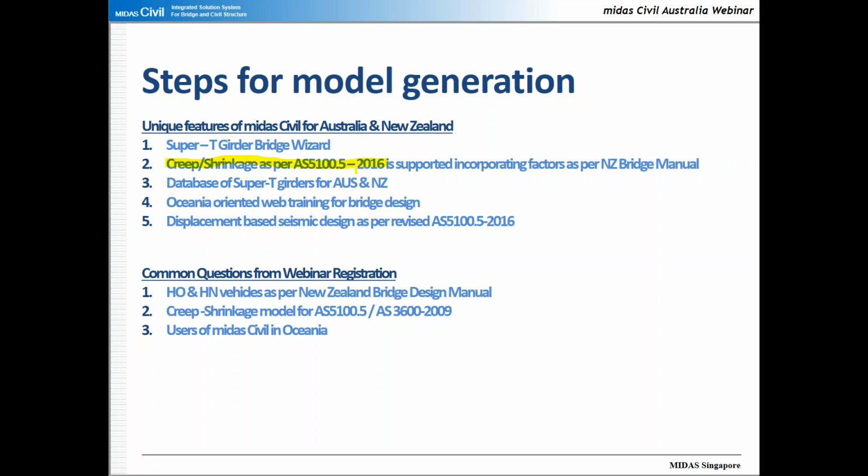And since New Zealand is following the creep and shrinkage model in AS5100 Part 5 with some changes, I would like to mention that you can even incorporate those changes as per the New Zealand Bridge Manual, and you can simulate the creep and shrinkage. You can simulate the time dependent effects as per New Zealand.